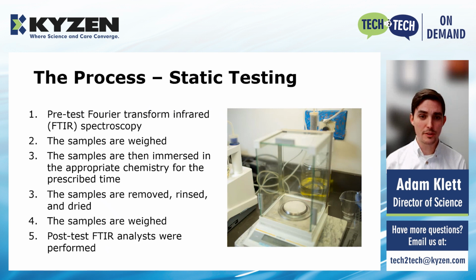The first thing that we do is we take an FTIR spectrum of the sample, a Fourier transform infrared spectroscopy spectrum. For those of you who aren't familiar with FTIR, we're essentially looking at the chemical makeup of the material to see if there are any changes. So we'll want to take a pre-test spectrum and then a post-test spectrum to make sure that the chemistry of the material hasn't changed much.